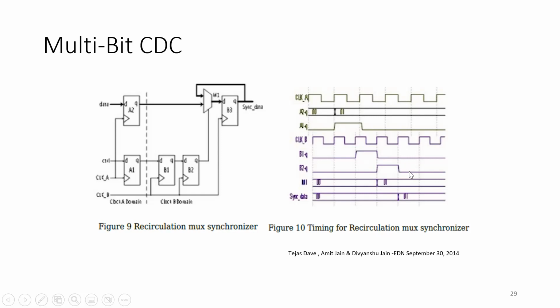That is happening in here. When the next one received the high, it opened this gate because this mux has two inputs, input 0 and input 1. If I have 1 coming from this B2, it will open the stream for this Q to go to the output. And it did go to the output, as you can see the change in output.